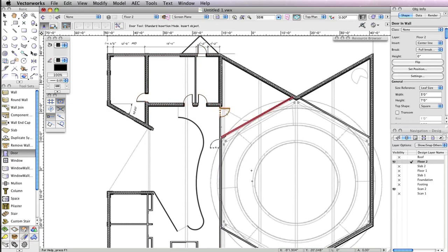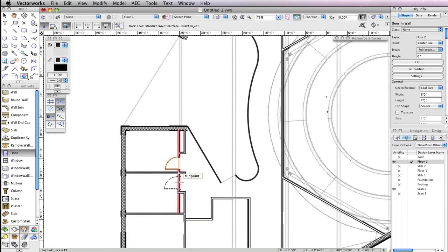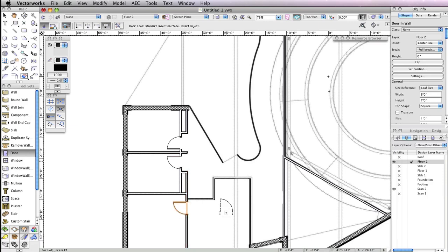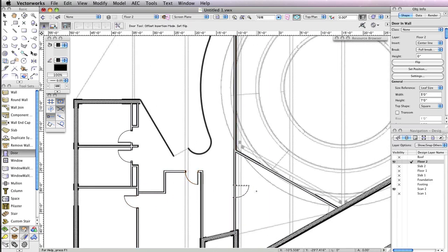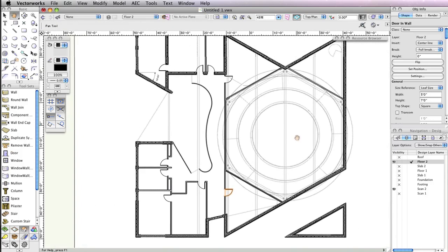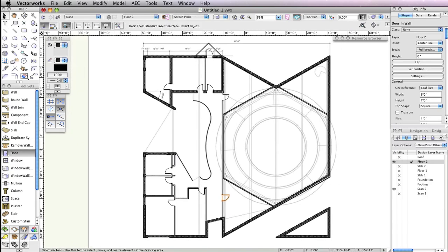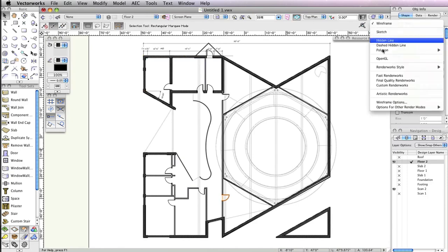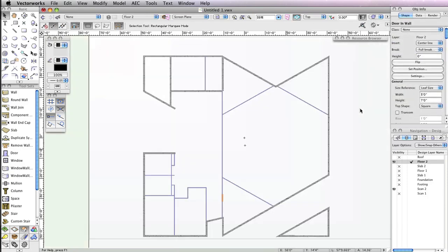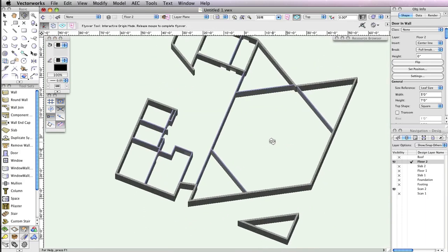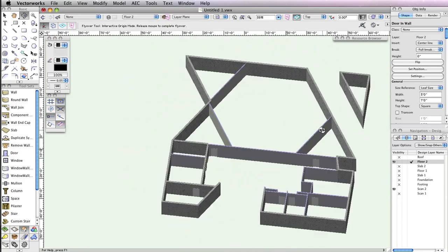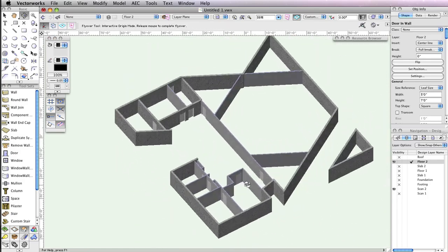Again, don't forget to use the opening shown in Scan 2 as a reference. Also, remember that the flip for the doors in your file should match that of the doors shown here. Here's what you should have when you're done. That's it for the doors. You can now render in OpenGL and take a look at your progress with the flyover tool. Then return to a top plane view when you're ready to move forward.